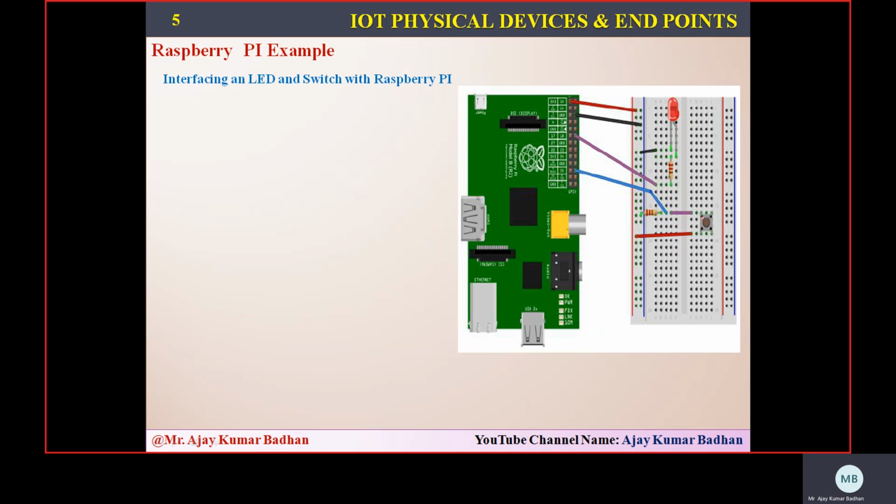So here you can see this particular bulb we are connecting. Since here also I am going to use pin number 18 for the output, that pin I have connected to this. You can see this particular bulb is provided. This is a switch, and here there is a red color line, and this line parallelly I am connecting here. This is connected to a particular voltage. What voltage? It is given here as 5 volts. This is the power line. And then I wanted to use the 18 power, so this one is connected to pin number 18.